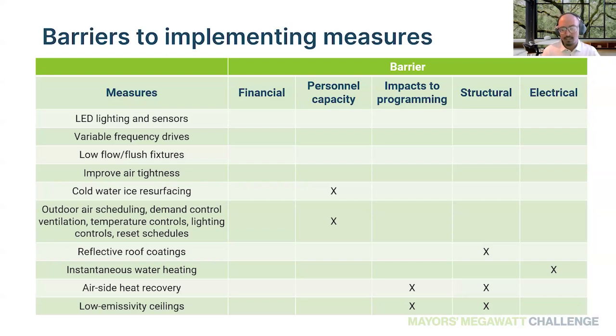which can lead to situations where you have a long running stream of, whether you've forgot to set the outdoor air schedule and you're having 24/7 outdoor air coming into the facility because you weren't sure of how the controls were quite set up. And you want to make sure this training and onboarding is critical.